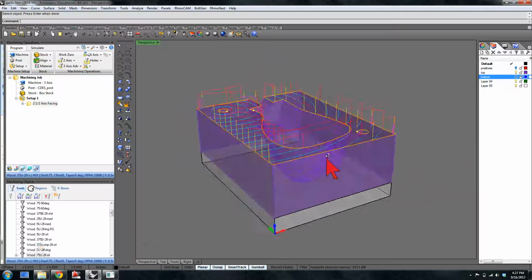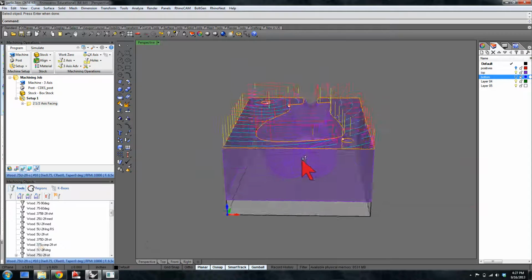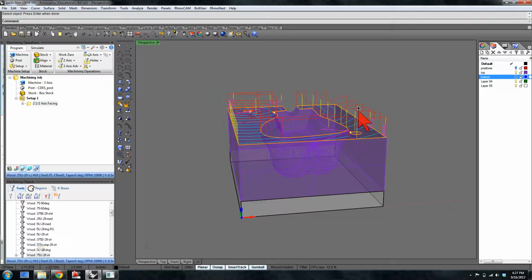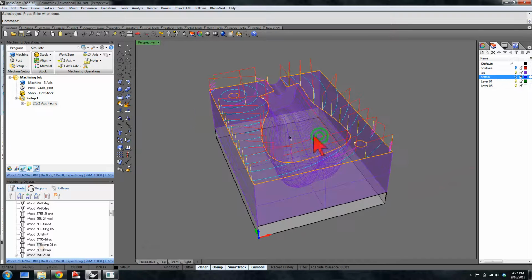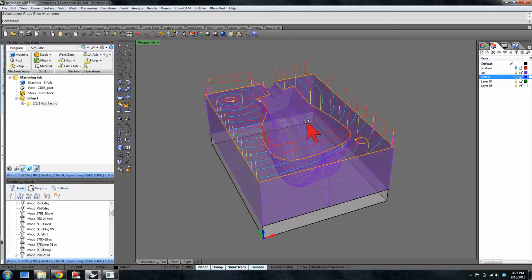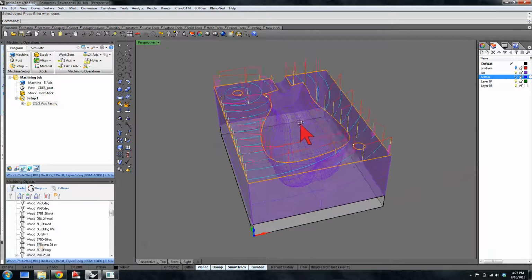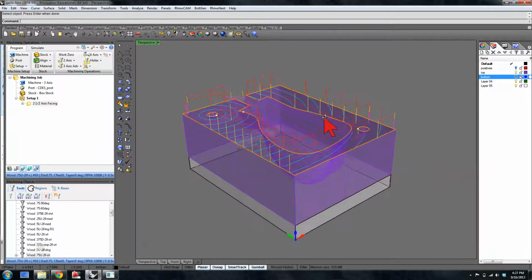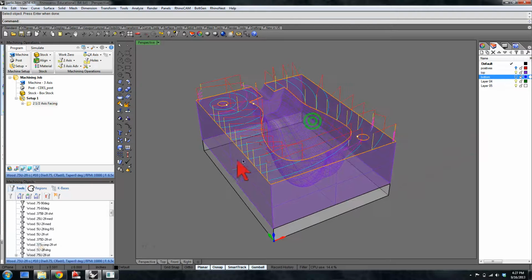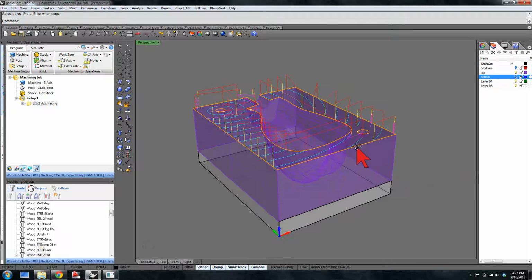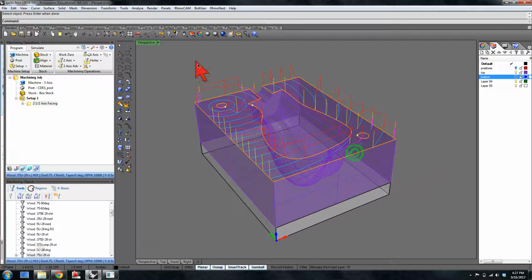This is a somewhat curious tool path. You can see all of these yellow lines and red lines are the bit going up and over the material and up and over this void in the center. We actually want to cut away that void in the center, so I have a single flat block. So as a result of having used this flat machining surface, we ended up with this toolpath, which is not exactly what we want.